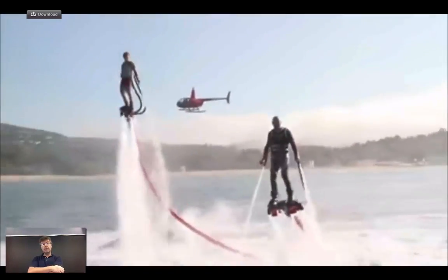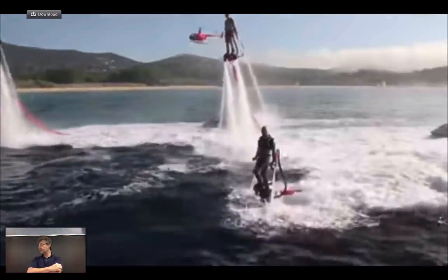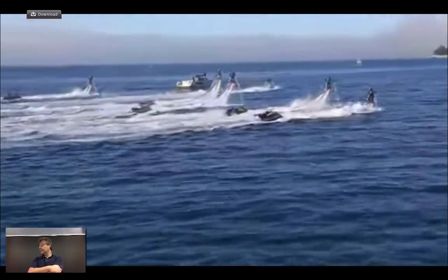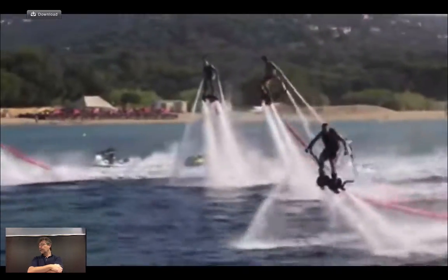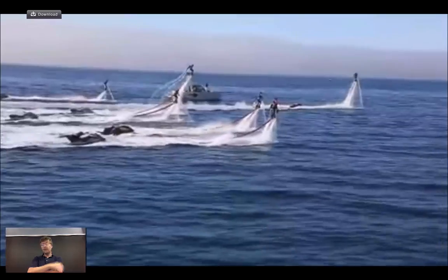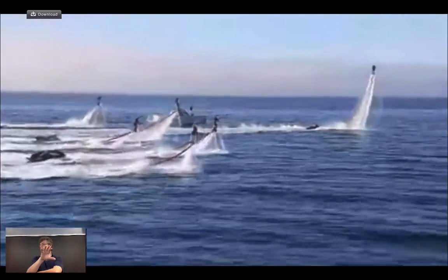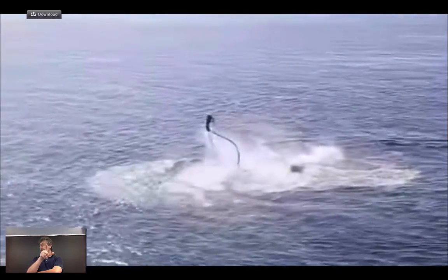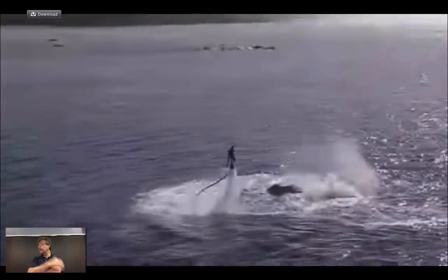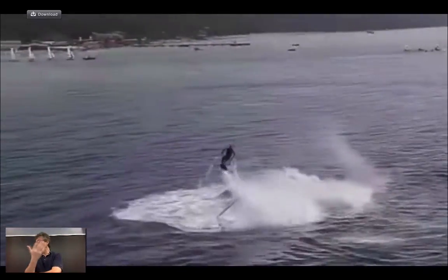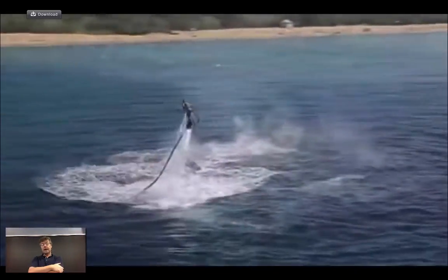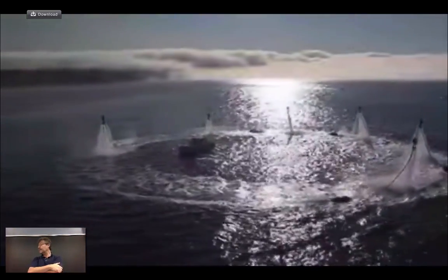And so when we talk about external flows, which is the topic that we'll talk about after we finish pipe flows, it's really very similar. It's basically looking at flow equivalence through the Reynolds number. And then once you have the right flow regime, you look at dynamic equivalence, and that dynamic equivalence, again, is a kind of Euler number. It is the Euler number, a much more straightforward Euler number than friction factors that we've used in pipe flow. So they're basically the same problem.